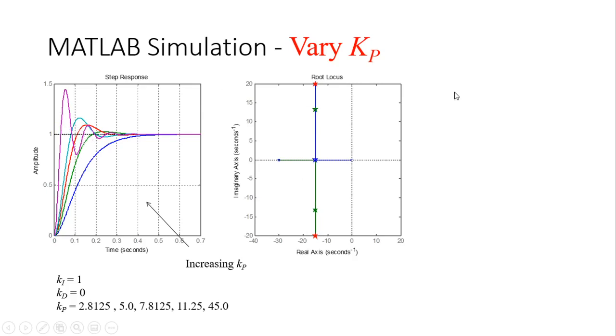So what does that mean? What is an underdamped system? When you have complex roots, right? They have the same real part. Remember what the response looks like? It will have something like e to the negative zeta omega n t. So this is your zeta omega n, the real part, and zeta omega n also controls the settling time.